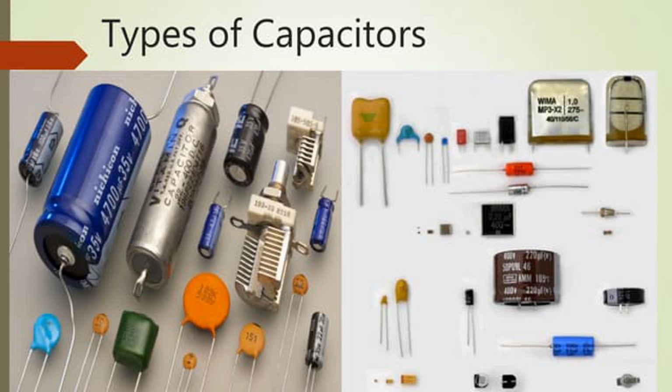Voltage rating is an important specification when considering electrolytic capacitors. It indicates the maximum voltage that a capacitor can safely withstand without experiencing breakdown or failure. Exceeding the rated voltage can lead to electrolyte leakage, capacitor failure, and even possible explosion or venting of gases.